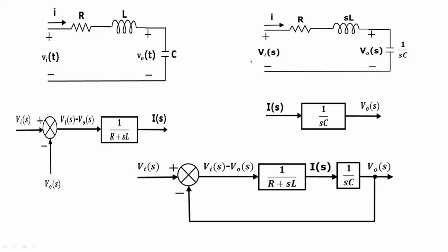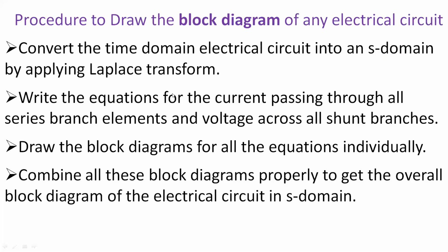Similarly, we can draw the block diagram of any electrical circuit or system. This is the procedure that is followed: convert the time domain electrical circuit into an s domain electrical circuit by applying Laplace transform. Write down the equations for the current passing through all the series branch elements and the voltage across all shunt branches.